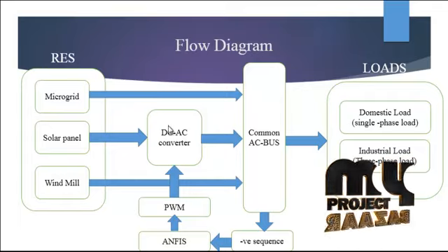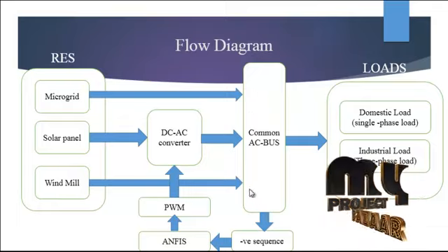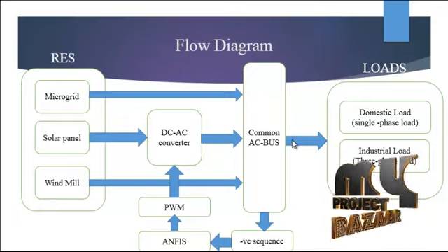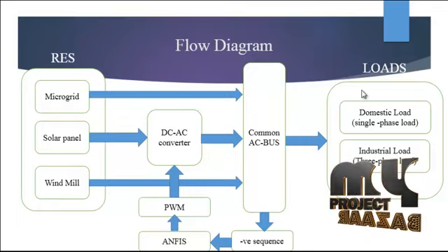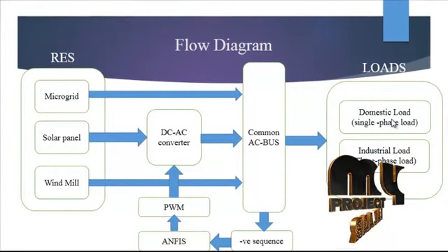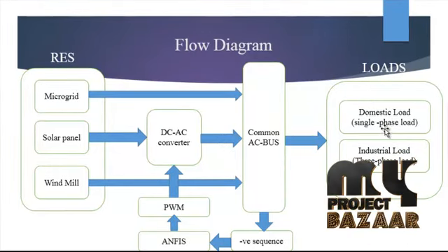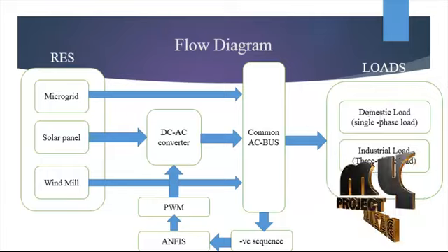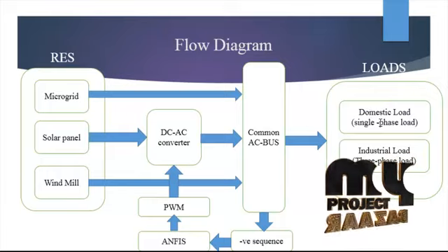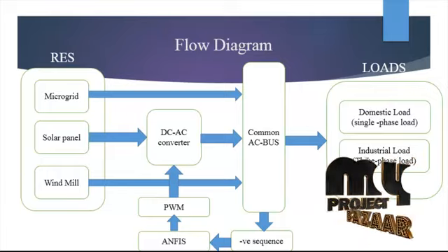These are commonly connected to the common AC bus. The common AC bus interfaces with the loads. We can connect different types of loads: domestic loads and industrial loads. Domestic loads are single phase loads and industrial loads are three phase loads.